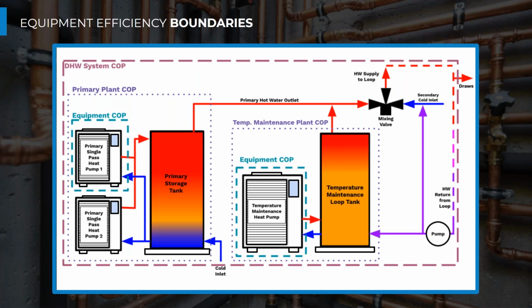But the typical hot water circulation loss rates in multifamily buildings, new multifamily buildings, range significantly. I've seen some at 40 watts per apartment unit, all the way up to 400 watts per apartment unit. Our typical range is closer to 75 to 90 watts per apartment. That's a good rule of thumb to base your system design off of, right around 90 watts or 100 watts per apartment. Sometimes we see it closer to 75, but we like to be conservative as engineers, of course.